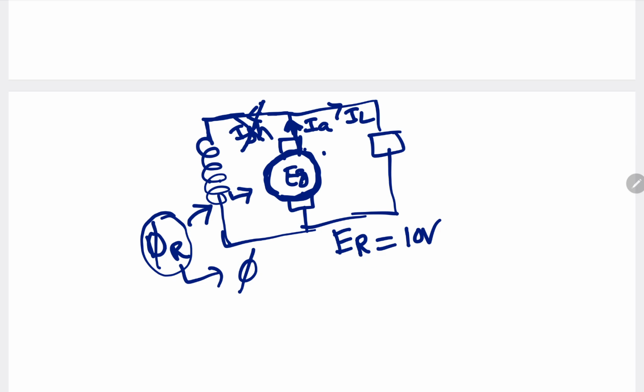That means in self-excited DC generator, initially we get the output due to the residual flux. Let us say if residual flux is absent, if residual flux is 0, then what do we have to do? Obviously we have to give some power supply to the field winding externally. This is called the voltage build-up process in the self-excited DC generator.